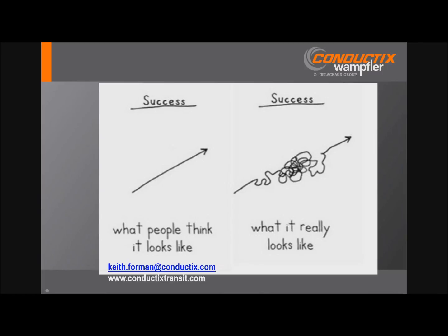Do you advise the rails to be positioned the same distance with respect to the guideway surface, or is it advisable to have them moving up and down? This is a very good question. It depends on the collector configuration. Excellent question, and I really appreciate it because I failed to mention this. Remember, the collector shoe that I showed was worn very significantly in one location. If you're familiar with overhead systems with pantograph collectors for transit, as you sit in the train and watch that overhead line, you'll see that it moves, and this is to provide good even wear.